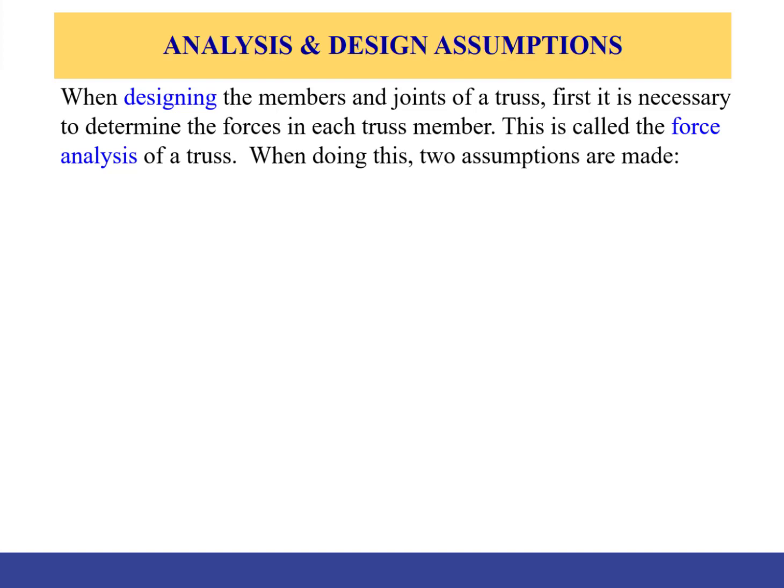Now, as we mentioned, the analysis of trusses plays an important role in the design: picking the right material, picking the right geometry, cross-section, and also length, and also configuration. Now, this is called force analysis, and the force analysis, for a fixed or known geometry, will provide you with the magnitude of tension and compression in each one of these members that constitute the truss.